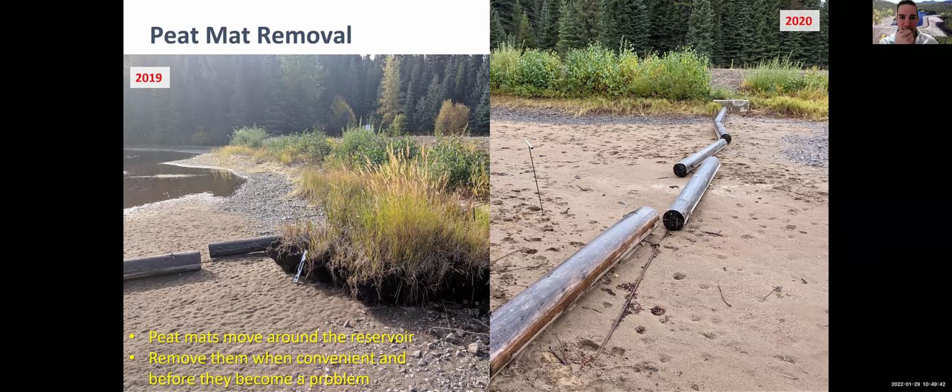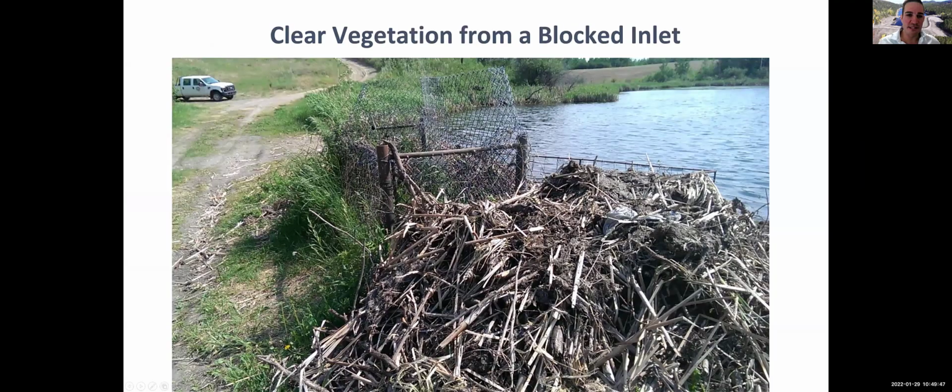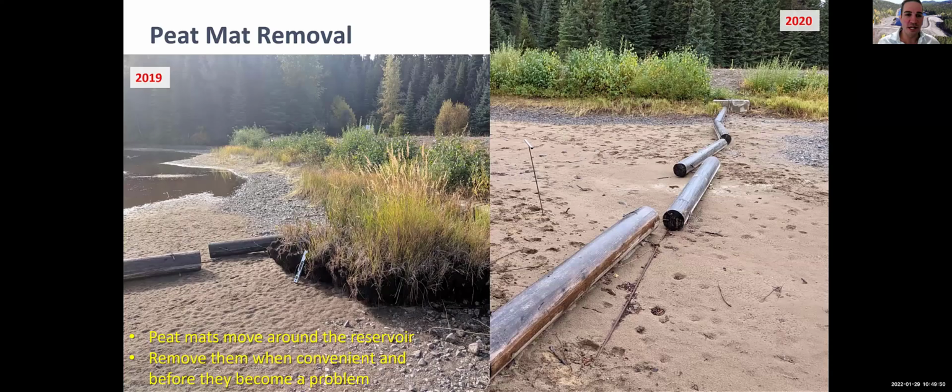Yeah, in this photo too, you can almost see the sign. I don't know if you can see my mouse there, but that's the dam safety sign, and the spillway is right here, and it goes out the other way. And so had that got past the log boom, it's going to go around that corner. It's quite a narrow concrete control section. If that plugged that up, that would be enough to take out a good amount of its capacity. So anyway, it's doing what it's supposed to do. But once it does, you need to still take the debris out. Otherwise, you're not helping yourself. That loading will break your boom, and then your boom might be part of the debris going in.